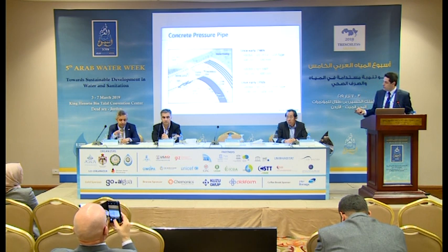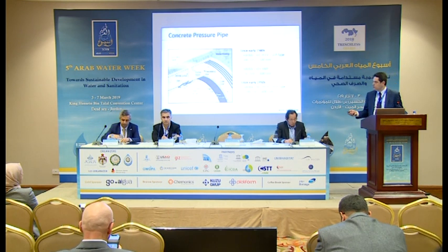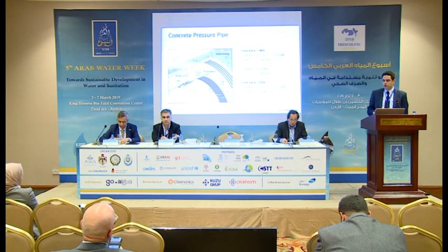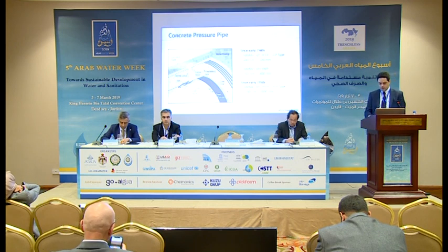And on top of that, there are the pre-stressing wires, or sometimes non-pre-stress reinforcement, that are wound on the pipe to give it the pressure capacity. And the final component of it is the mortar coating, whose job is to protect that reinforcement from corrosion and the environmental factors.